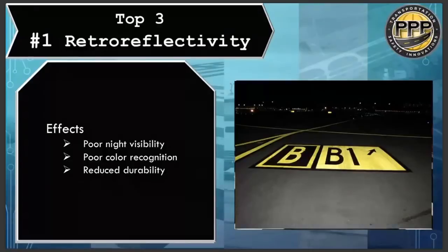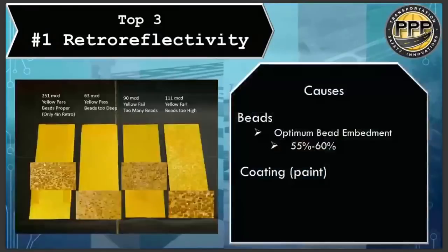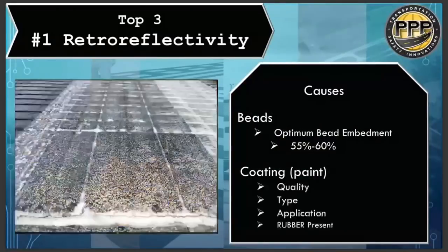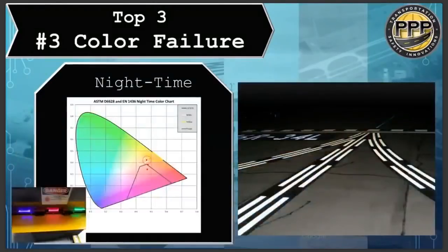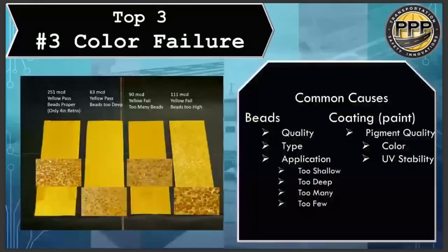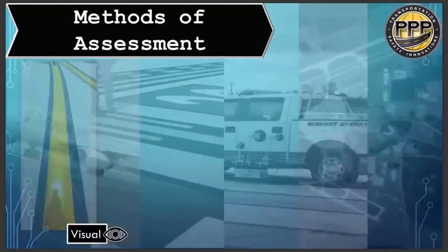Just as Greg said, when they're under embedded, they very often tend to reflect light rather than the color of the coating because they're not embedded in that coating. So just like Greg said, he nailed it. When the application is a little too fast, paint's too thin, beads are sitting on top and reflect a color other than what it is.